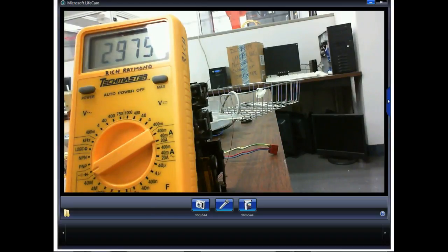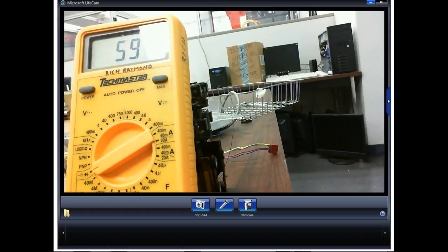So this is an open, right? So now it's acting like an open. And now it's acting like a closed switch. It just drops a little bit of voltage. A closed switch will drop 0 volts, right? You understand that? A solid state device will never drop 0 volts because it's not a closed switch.